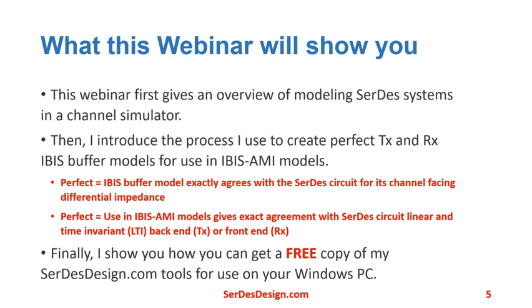Perfect also means that use of this IBIS buffer in IBIS-AMI models results in exact agreement with the SerDes transmit or receive circuit LTI characteristics. Finally, I show you how you can get for free the tools I use to create perfect IBIS buffers and use them to create perfect circuit IBIS-AMI models.